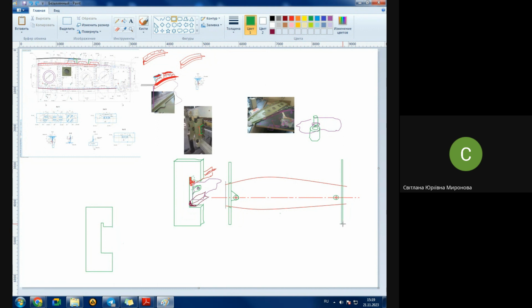Something similar, no? As I try to show you on this side. And depending on the length of your item, let's imagine it's 1 meter. If it's 1 meter, approximately each 50 centimeters, better to place one more locator. It depends on the size and on the stiffness of your structure, how many locators you need to place here.